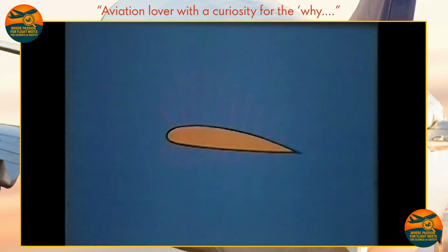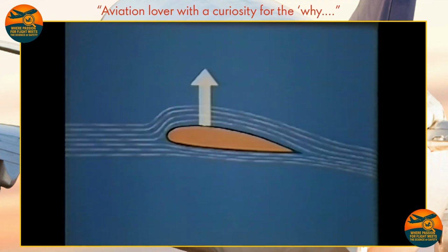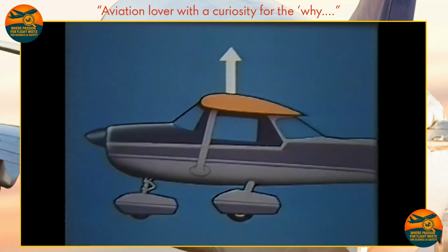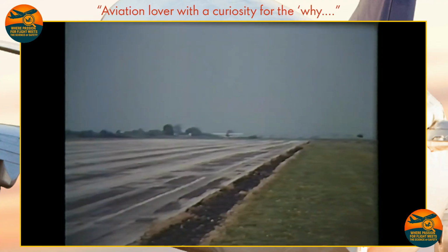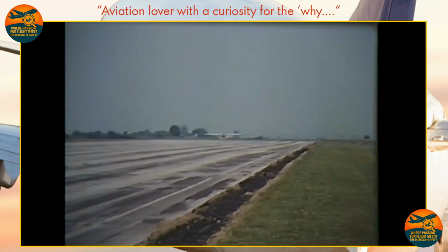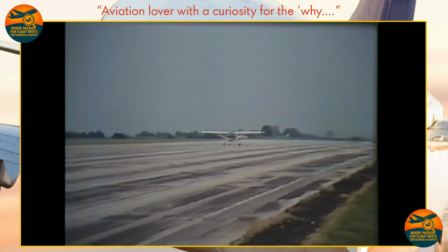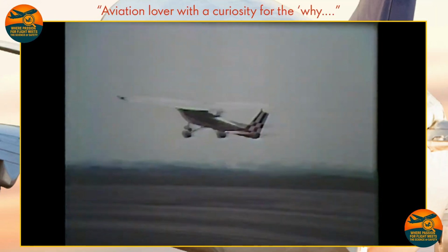The resultant lift force acts through a point we call the center of pressure, and at right angles to the relative airflow. And so we have a cambered wing flying at a small angle to the horizontal, producing a resultant lift force exactly equal to the weight of the aeroplane in steady level flight. Lift increases with speed. We prove it every time we take off. It also increases with an increase in the angle of attack.